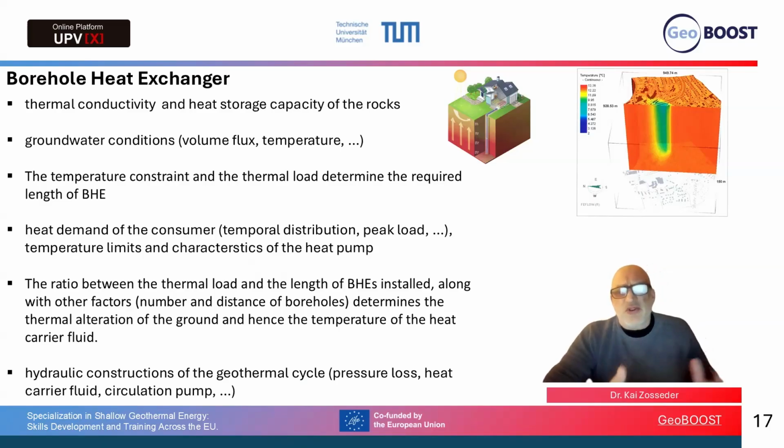So it is important to know the heat demand of such a consumer: the temperature distribution of the heat demand, peak loads, and so on. Temperature limits must be known also for the characteristics of the heat pump. And then the ratio between the thermal load and the length of the installed borehole heat exchangers is crucial, along with other factors like the number and distance of boreholes.